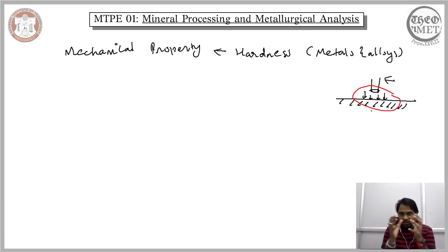So essentially, hardness defines the ability of a material to resist any local permanent deformation, which can also be referred to as plastic deformation. This is the definition of hardness in the context of metals and alloys. In order to do so, you introduce an indentation through an indenter, and you relate the load and the indentation that is being formed.